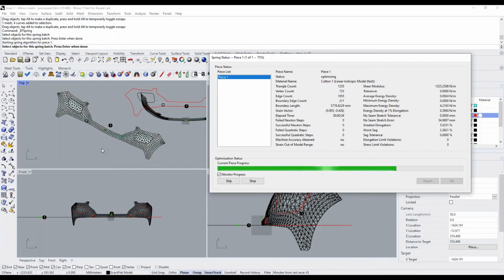The reality of the exact flat flattener is it's not a projection flattener. What it does is it actually distorts the 3D object through nonlinear transformation or deformation into your 2D pattern piece, such that when you wrap it back on, it fits perfectly. So the cutouts have to go through the same deformation process in order for them to be properly applied.